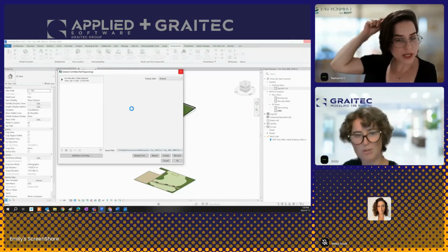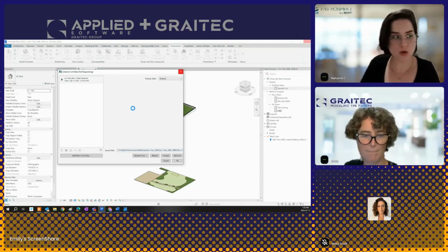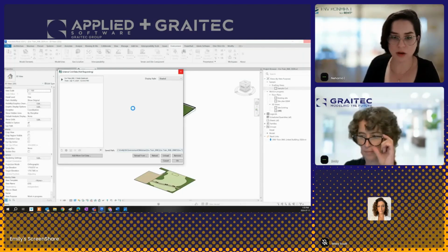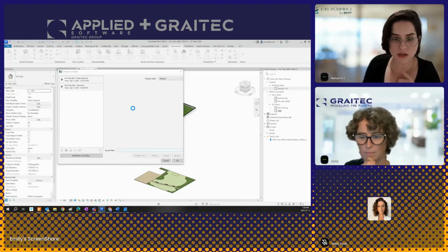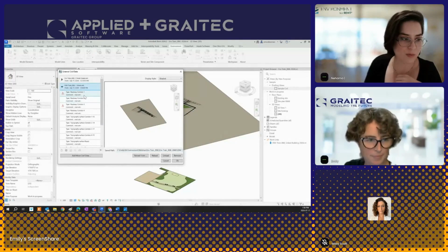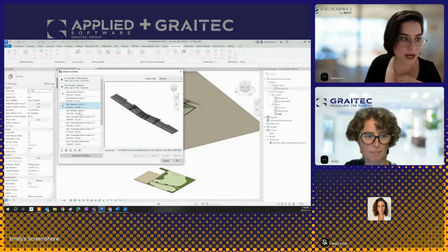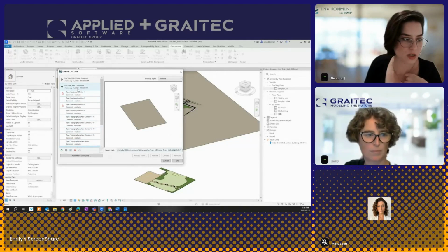Of course, it's also usually heavier if you're using the corridor itself, because basically a corridor in Civil 3D is a solid element, a lot of time with the layers of the paving, with the curbstones. So a lot of times I find myself only importing the thin surfaces from Civil 3D, which are the same elevation, but are kind of lighter. So it just depends on what exactly it is you need to import.